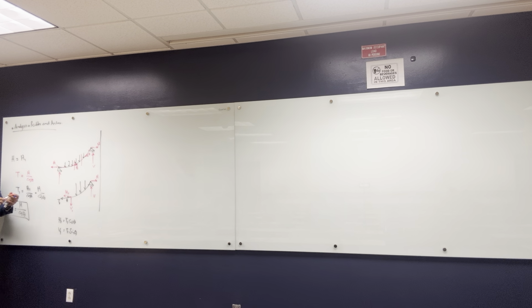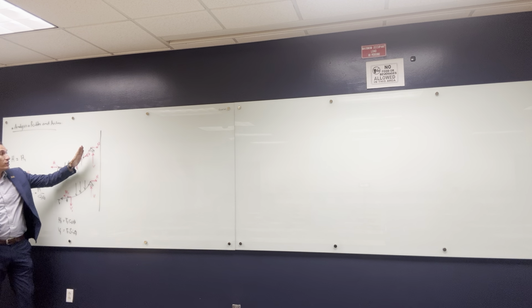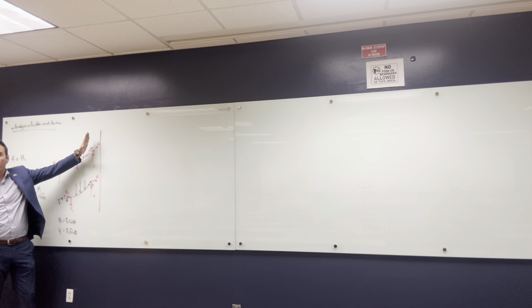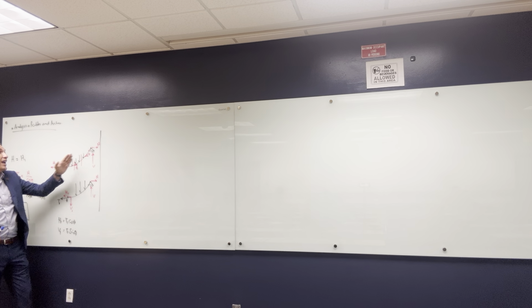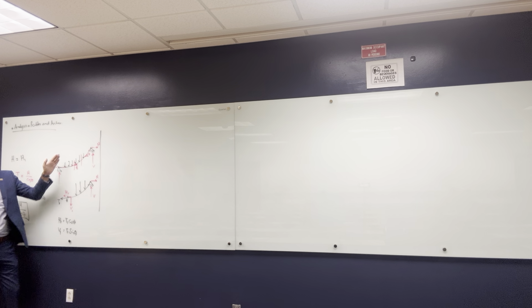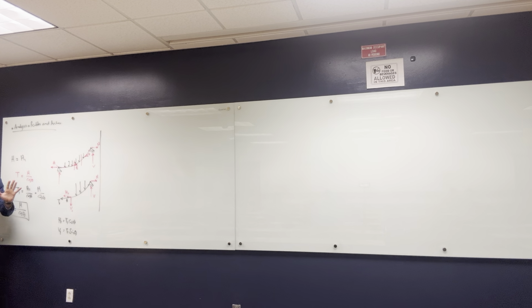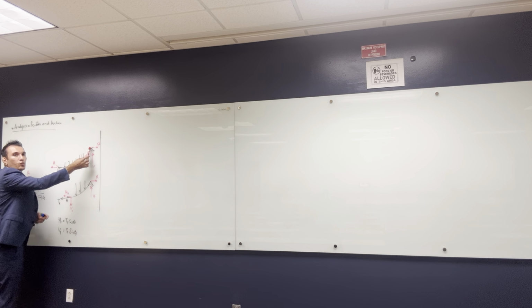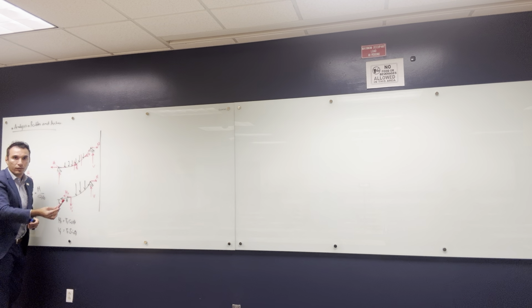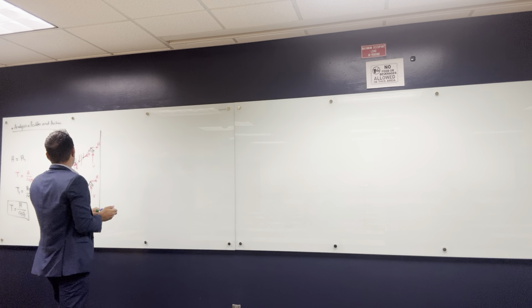So we said that mostly the maximum tension is at the support, because at the support we have the maximum theta. But I have two supports, so definitely it's one of them, the one that has the maximum slope. Which one of these might have the maximum tension? This support, or this one? It's the one where I have the maximum slope of the cable. All right, so let's put this into practice. I have an example here.